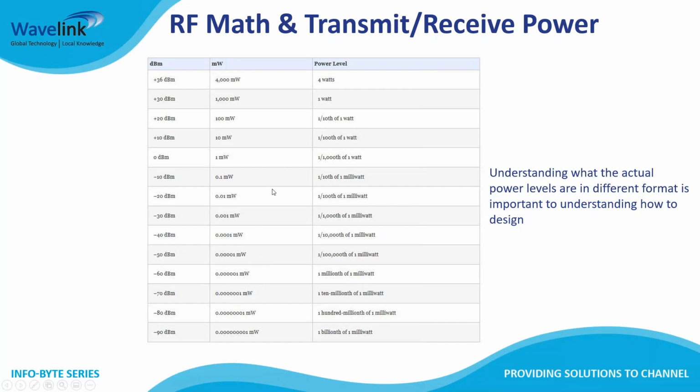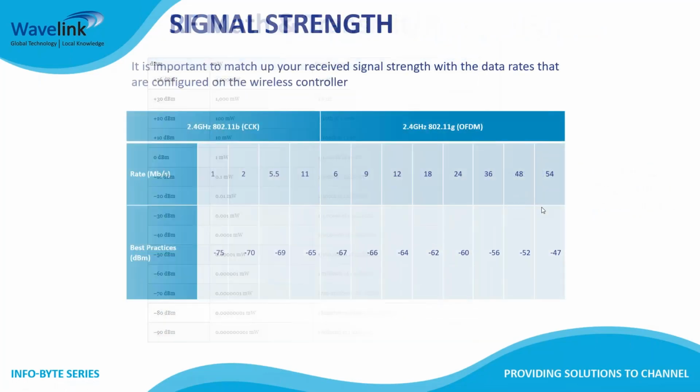Whenever we're looking at actual design, we're designing in the negative. A good threshold for a voice over Wi-Fi solution is between negative 30 dBm and negative 67 at a maximum. So the transmission rates themselves are very, very low.